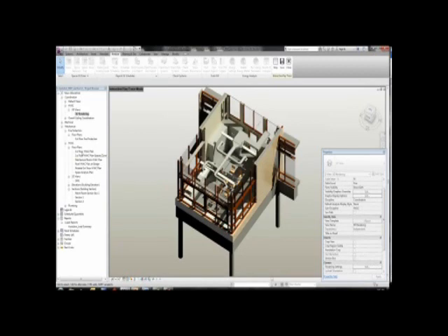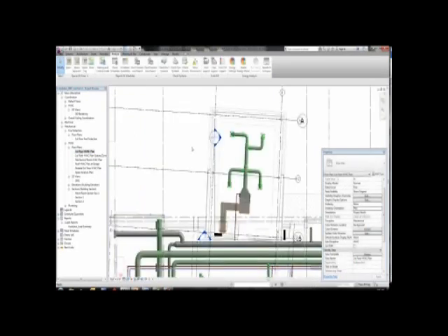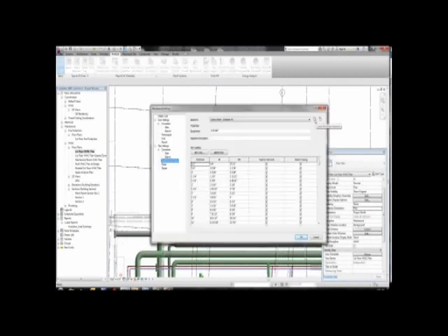Okay, now actually taking a look at the new features of Revit MEP 2013. I'm going to bring up a floor plan of the model, and we're going to start taking a look at pipe routing and duct routing practices. As I jump into the mechanical settings, you can see that when I click on the radio button, we now have options for new segments.